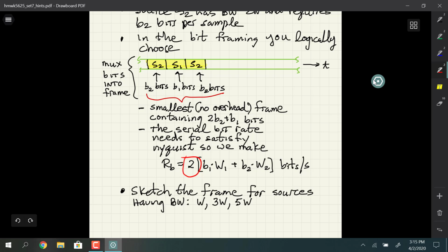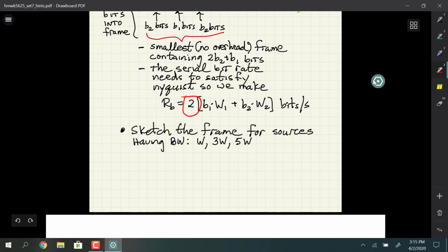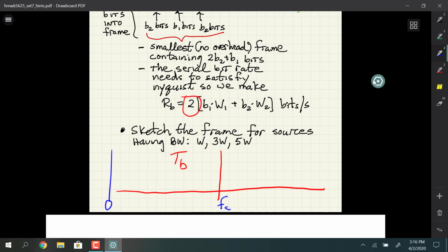And then the second part of the problem is, if you're going to transmit those bits, and those bits have bit period TB, if you're going to put them up on a carrier, and I'm just going to show this as a single-sided spectrum, but I'm going to suppose that's the carrier and somewhere down over here is 0. So the pulses, rectangular pulses, are of width TB. You know, from problem number 5 on the exam, the spectrum is going to be something like that.